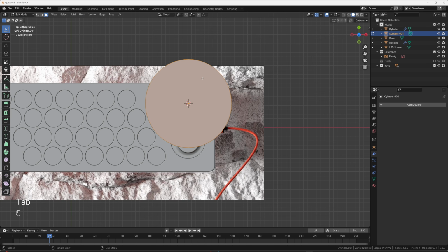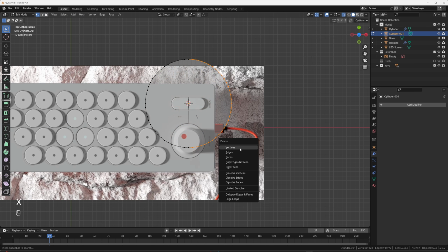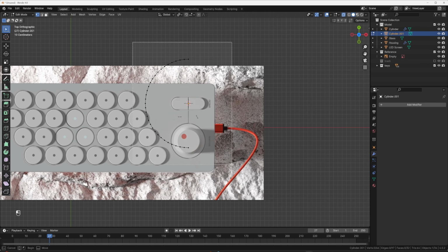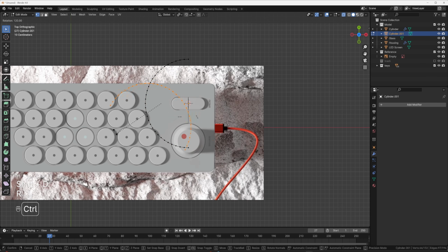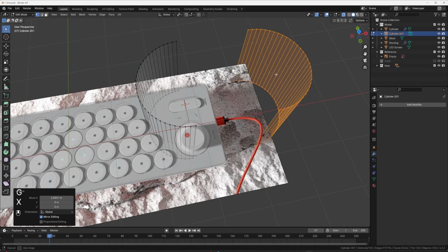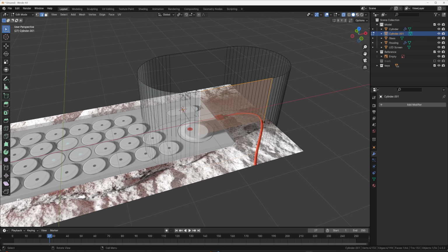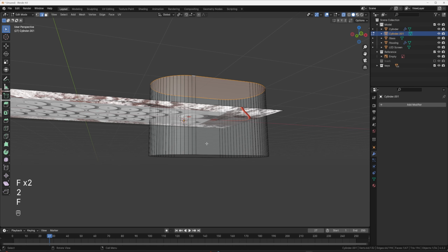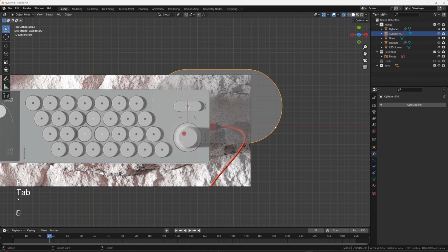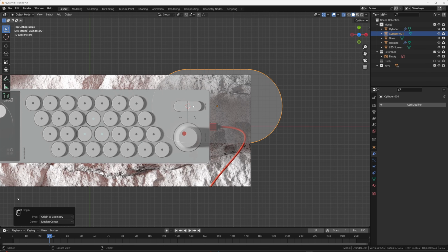And then what I want to do is tab, Alt-Z, 1, and then get rid of all of these. We're basically going to make this same shape. So delete the vertices, Shift D, R, around 180, G X, and then hit 2 to select these two faces and these two. Hold Alt on the top to fill, hold Alt on the bottom to fill with F. And then basically I just want to right click, set the origin to geometry, and then Alt G resets the position to the 3D cursor.